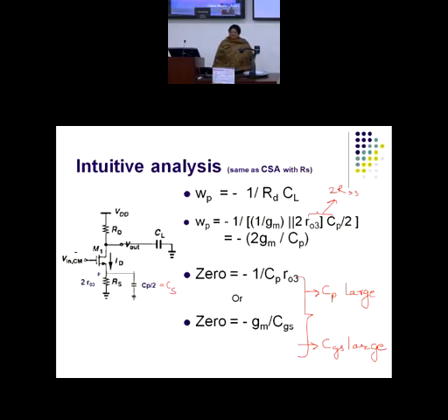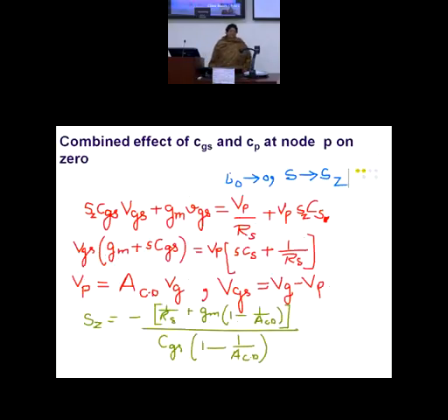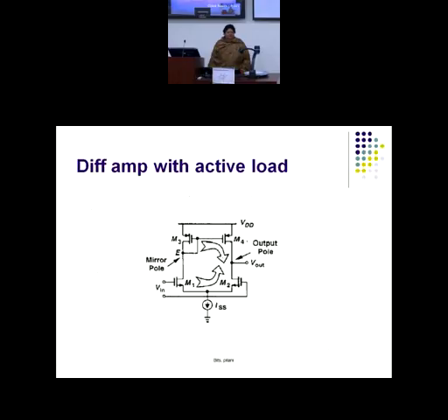Differential amplifier, that is the next slide, slide number 38. Now I am taking a different configuration. Single-ended output, slide number 38. Here you have asymmetry in the load. You have current mirror acting as a load. So again we have a node Vin, we have a node E. I will call this a mirror node. Node E is called a mirror node. And I have a node Vout.